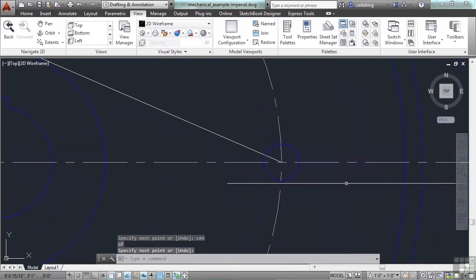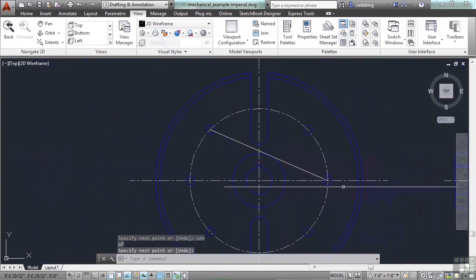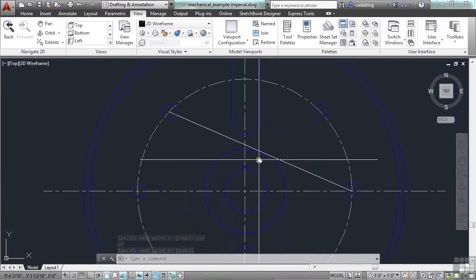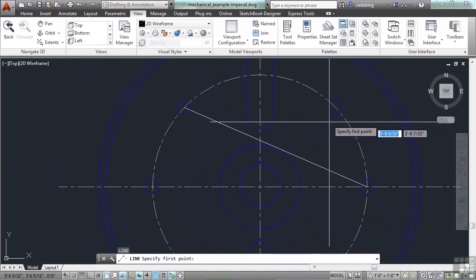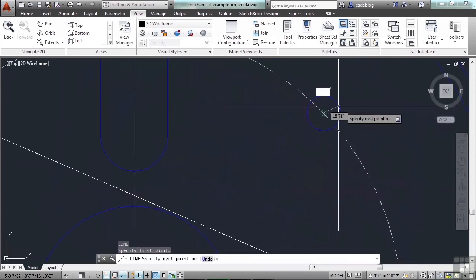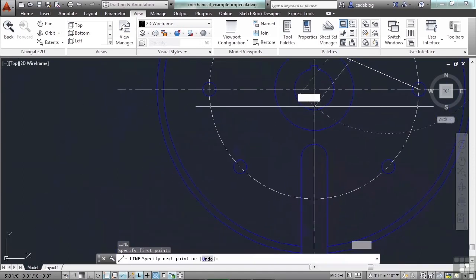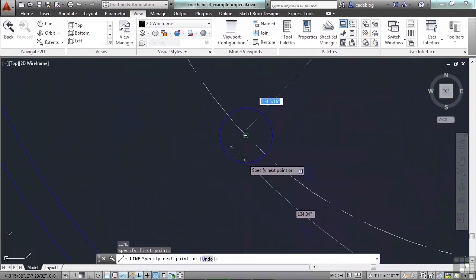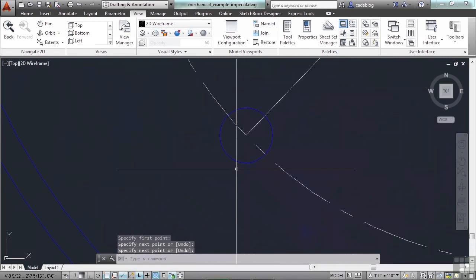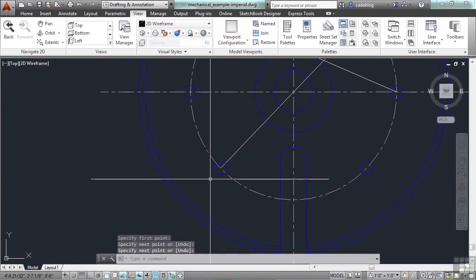And there you go. You can also use the scroll wheel. Zoom in and out, or pan back and forth transparently within a command. So I can zoom in, zoom out, pan, zoom back in. These are transparent commands. And ever since the scroll wheel became used in AutoCAD to zoom in and to pan around, I haven't really used transparent commands and thought about it in a long time.